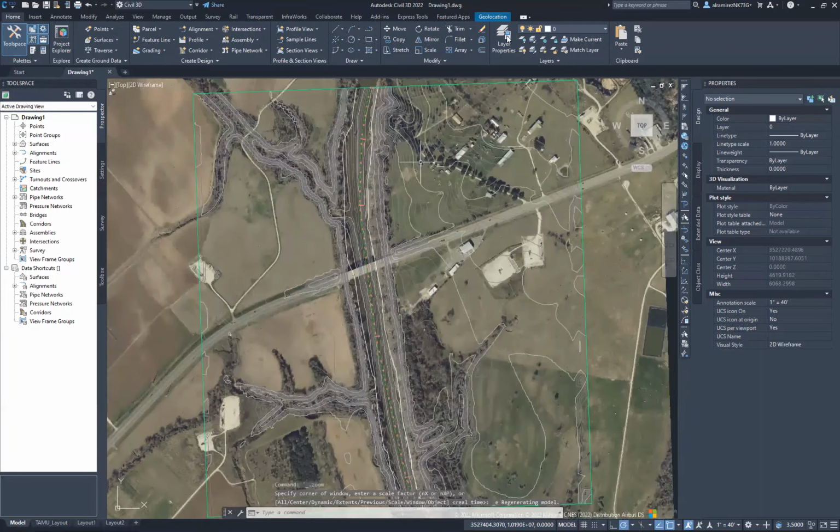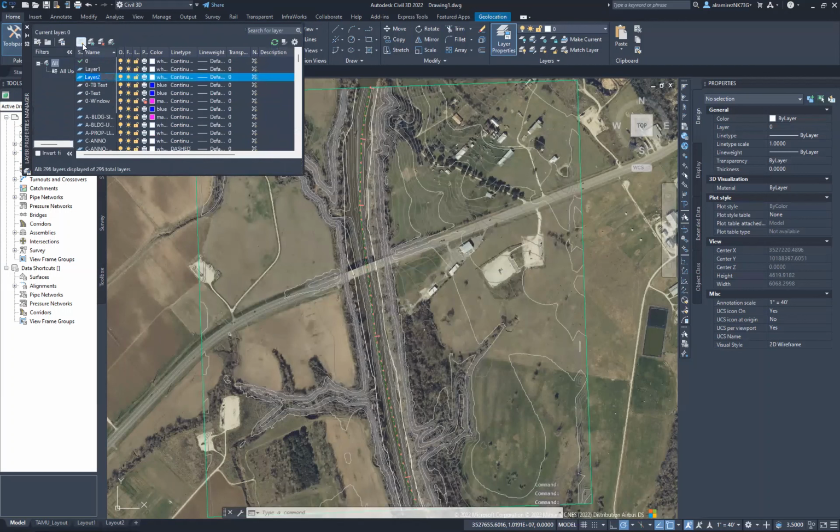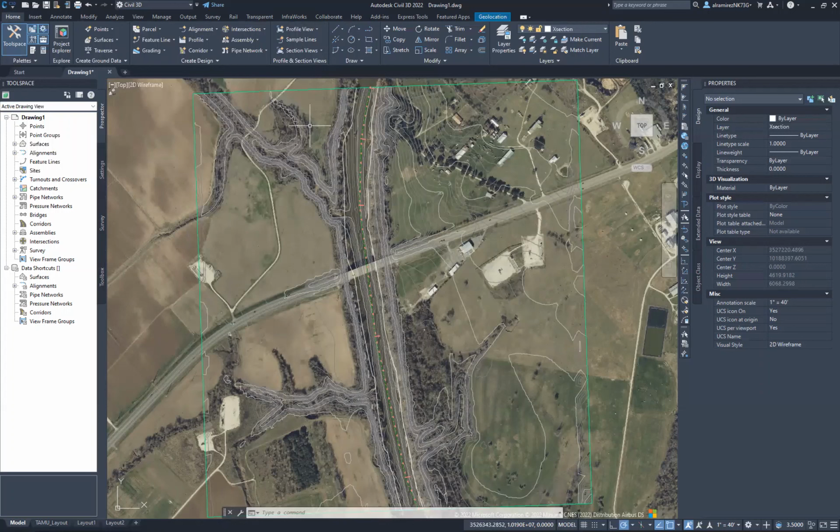Up next, we're gonna create a new layer. We call this cross section. Click on this little blue parallelogram to make it the current layer. Then we're going to use P-line, and we're just going to draw some lines going across this river. You kind of want one going across here. There's this road.